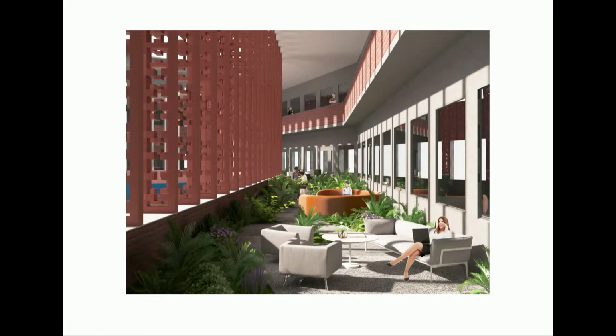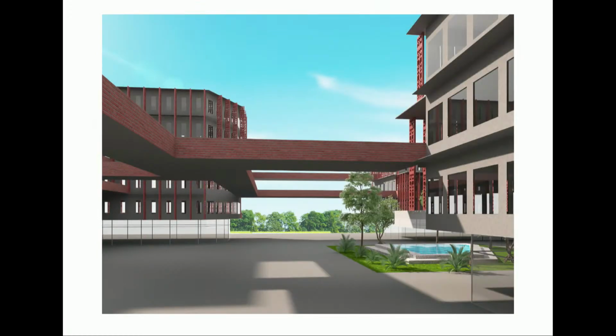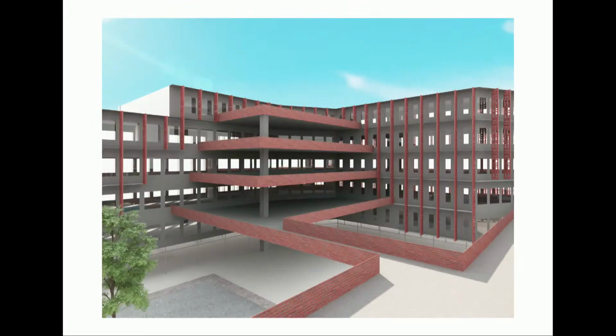And here are some design visuals. So this is the protected outdoor garden with the Jalis aligned at 30 degrees for the March sun to enter in. And these are some views from the skywalks, which have been created to give people different experiences around the site. And this is the view from the ground floor, where you can see there's a water body provided to allow for evaporative cooling and to lower down the dry bulb temperature.